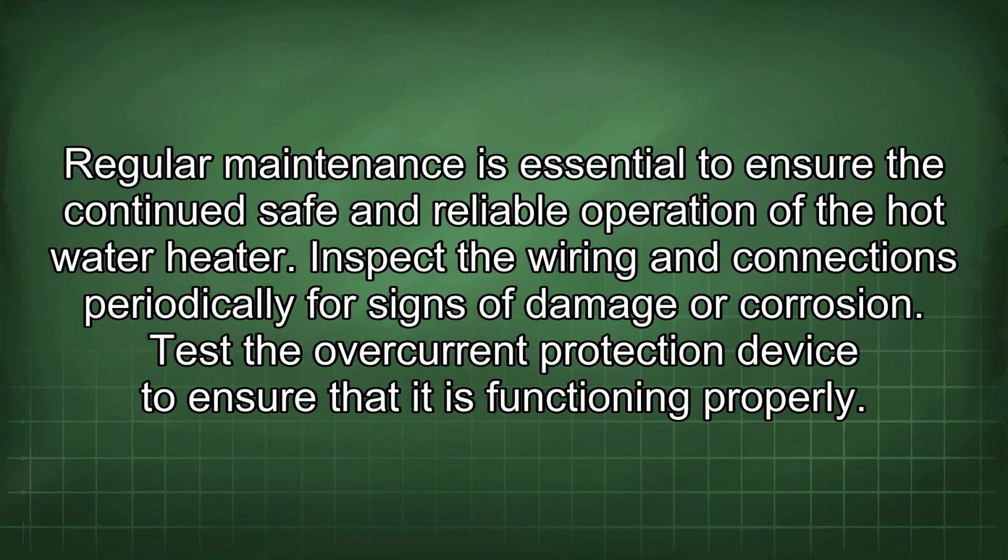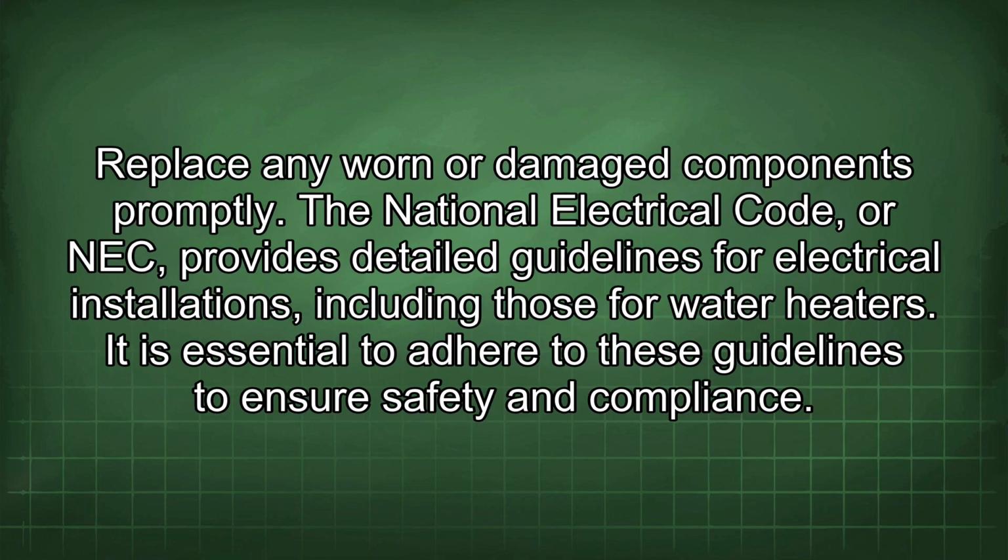Regular maintenance is essential to ensure the continued safe and reliable operation of the hot water heater. Inspect the wiring and connections periodically for signs of damage or corrosion. Test the overcurrent protection device to ensure that it is functioning properly. Replace any worn or damaged components promptly.